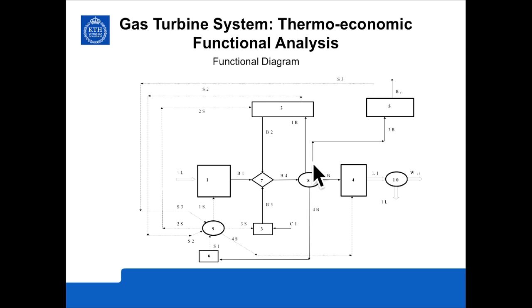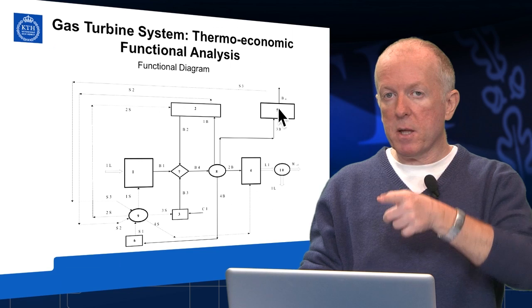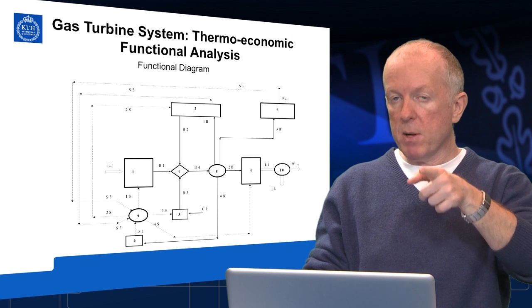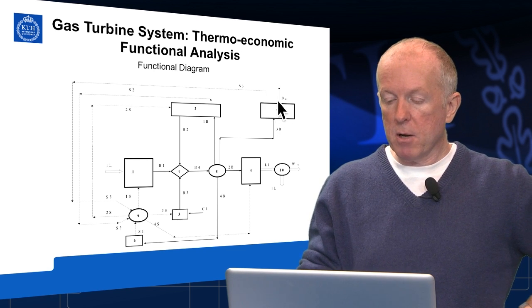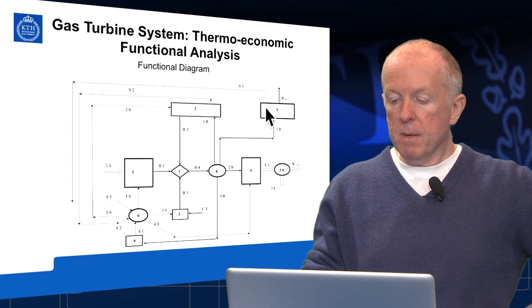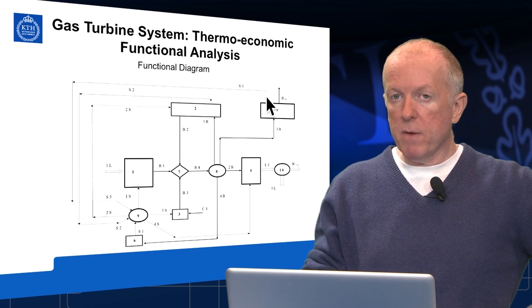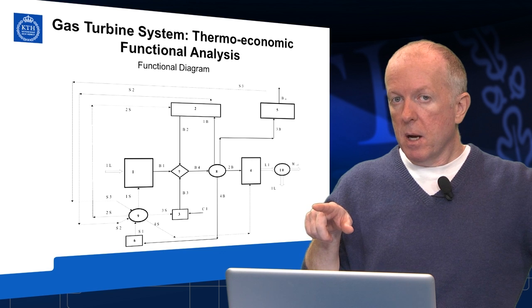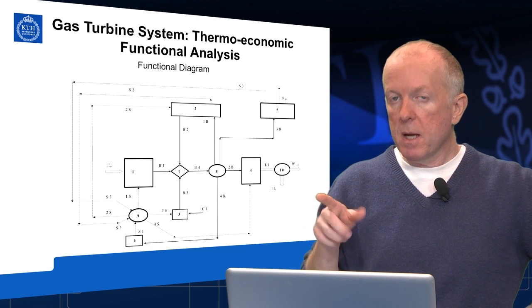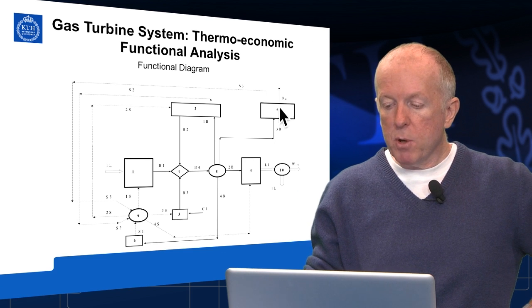The remaining part of the exergy from the branching unit 8 is given to the heat recovery steam generator. The heat recovery steam generator receives exergy, which is the difference of exergy between flow number 6 and flow number 7, and produces a product which is the steam. Still, consider that the heat recovery steam generator, because it reduces the entropy of the exhaust flow, is a dissipator of entropy, so it produces a negentropy flow.